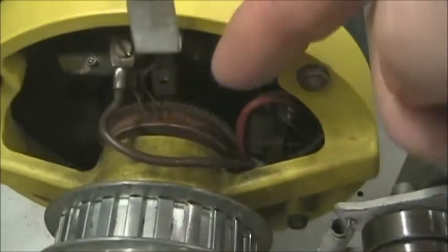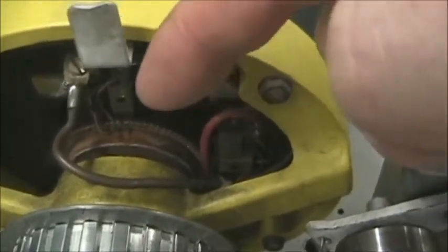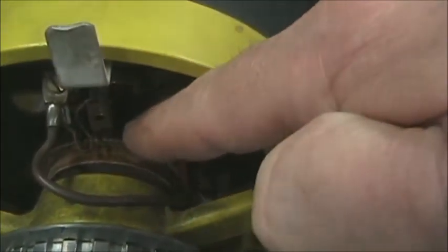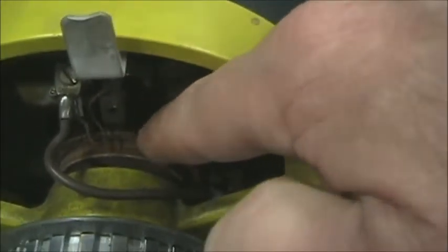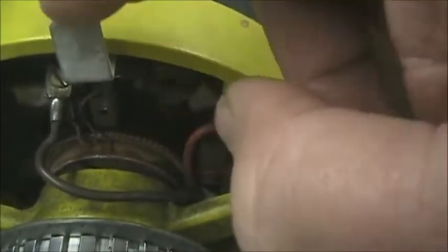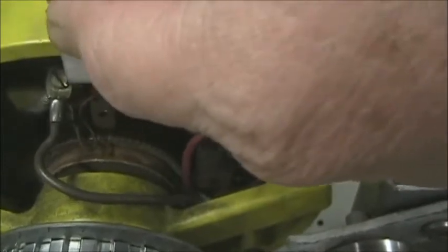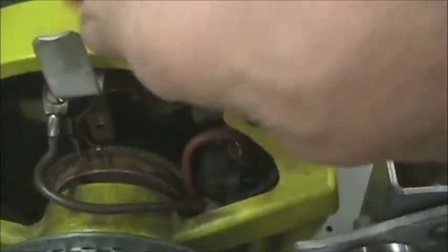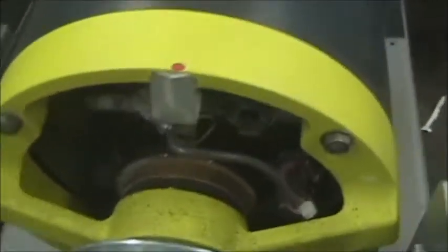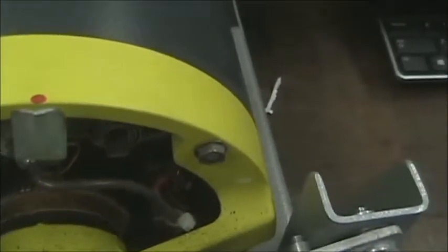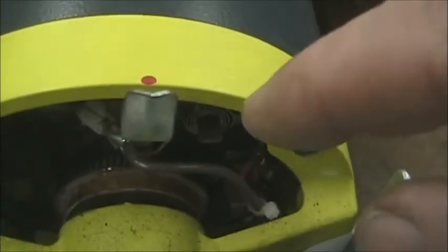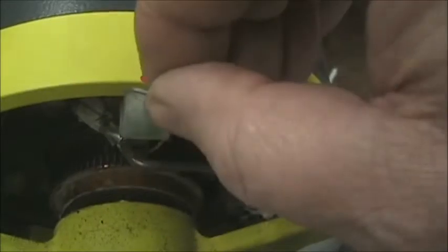So this is the DC machine that we have run data on. We see the brushes. We see the commutator down inside, and this is the brush positioning mechanism. We come over to the universal motor, and we see pretty much the same identical setup. The brushes, the brush positioning mechanism, and the commutator down inside the motor. So that's a view from the commutator side.